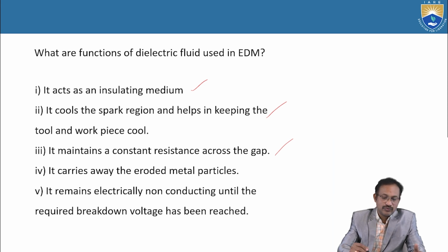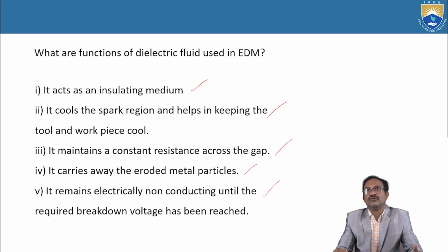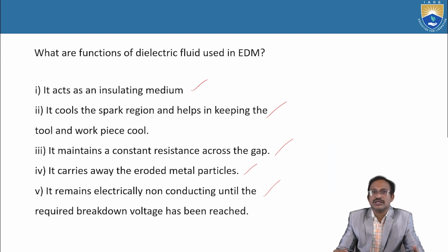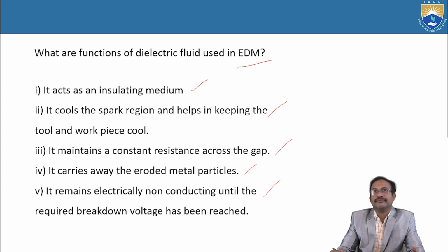Fourth, it carries away the eroded metal particles. Fifth, it remains electrically non-conducting until the required breakdown voltage has been reached. So these are the functions of the dielectric fluid used in electro discharge machining.